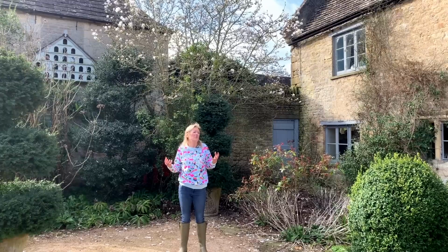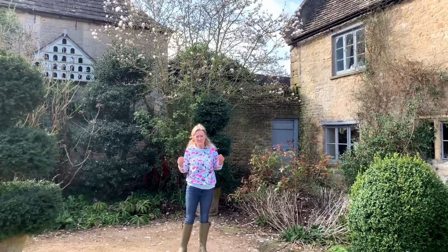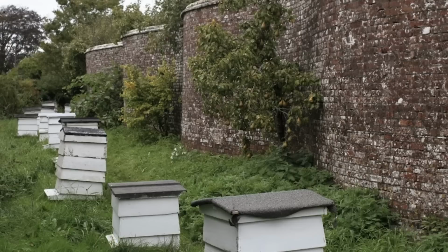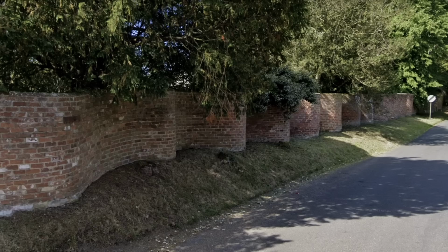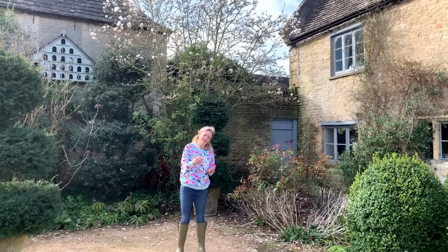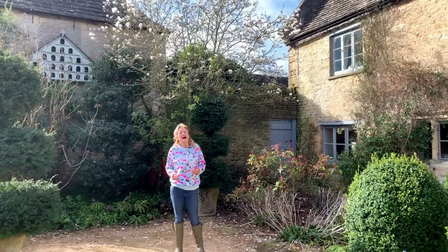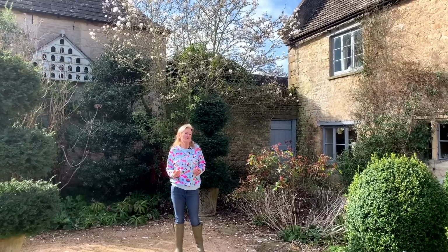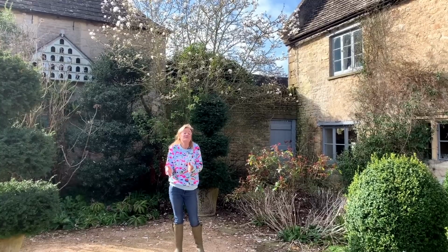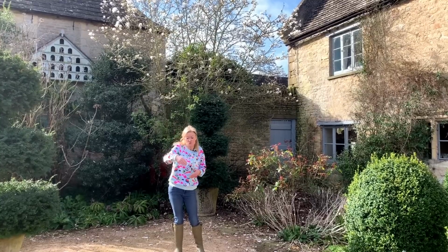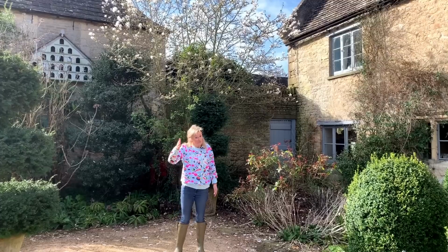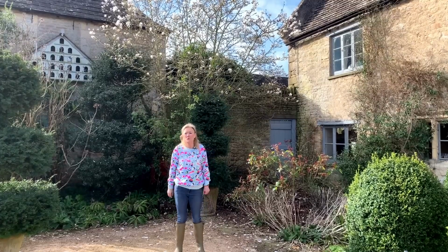The thing that people probably know most of is you get serpentine walls around walled gardens, and they're called crinkle crankle walls, and they're built like that partly because of the shape, and you get the nice bits of south and different orientations on that same wall, and also because structurally it's a much stronger shape. When you build it out of brick, you don't have to use so many bricks to get more structure in a serpentine curve than if you have a straightforward straight brick wall.